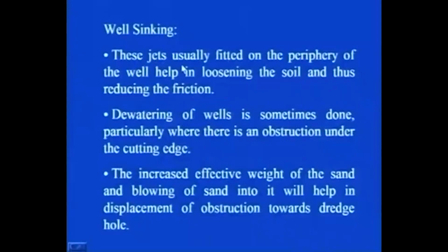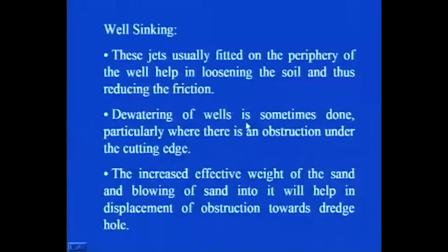Then these jets, they are usually fitted on the periphery of the well, and they help in loosening the soil and thus reducing the friction. So the water or air jets loosen the soil around the well and subsequently reduce the friction. Then dewatering of wells is sometimes done, particularly when there is an obstruction under the cutting edge. So dewatering also helps the process of sinking.